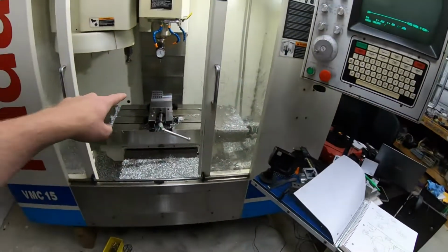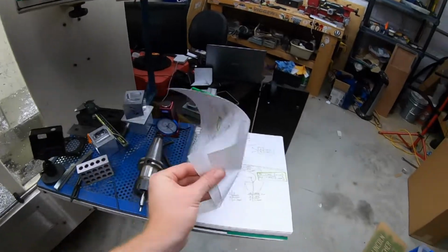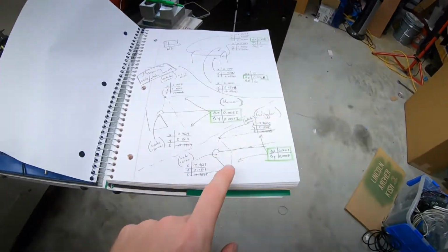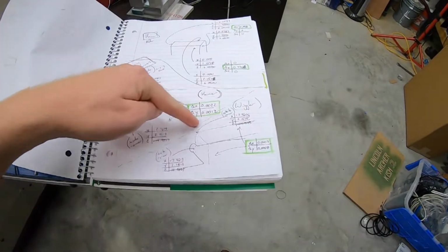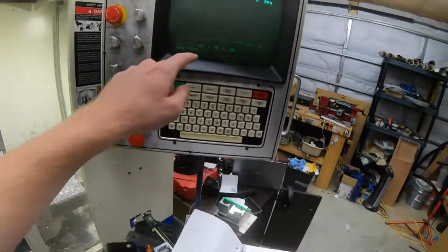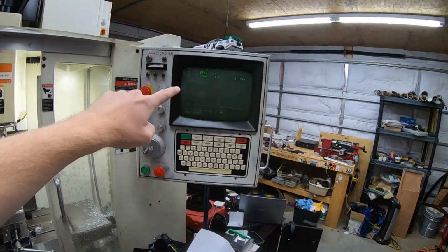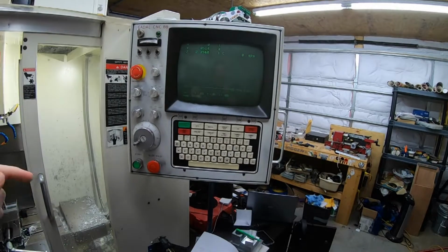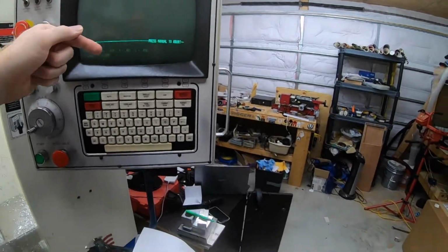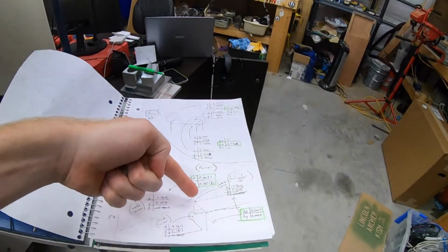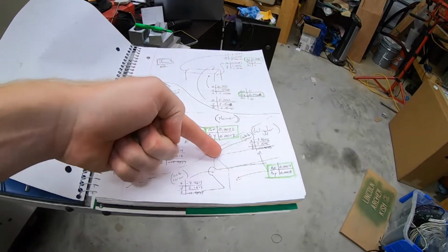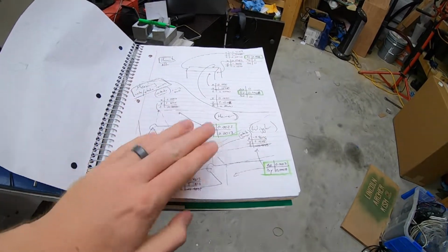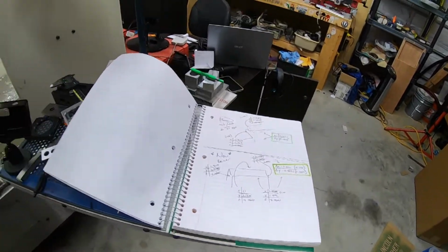I'm gonna do one more test similar to what we did before, where I checked the outside corner. I'm gonna use the utilities menu on here, and we're going to find the fixture offset for the X and Y for this outside corner, and then do the exact same thing for the inside corner. So here we go.